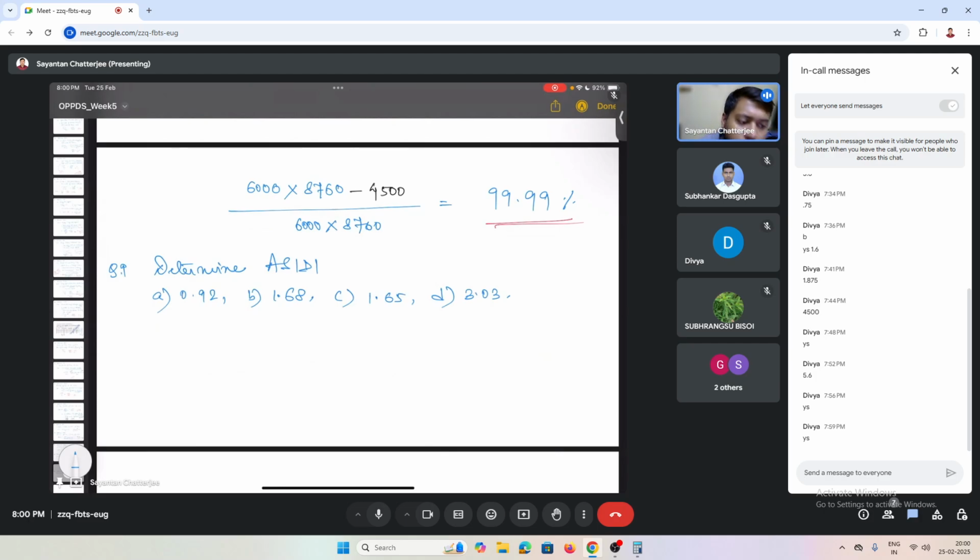Considering the power factor to be one. We have previously also discussed the same type of problem. So SED will be the total KVA connected times the duration of interruption.